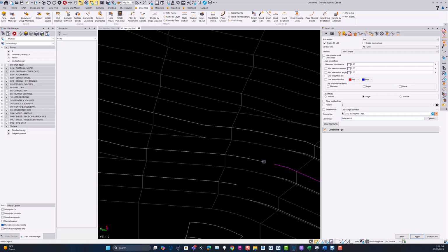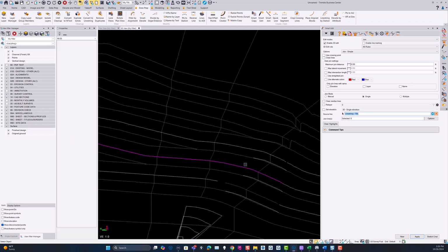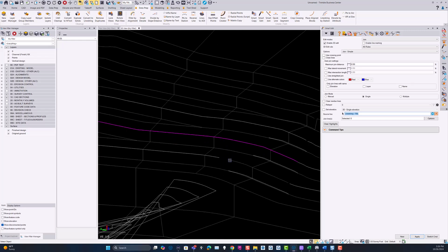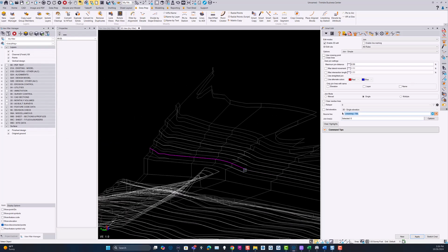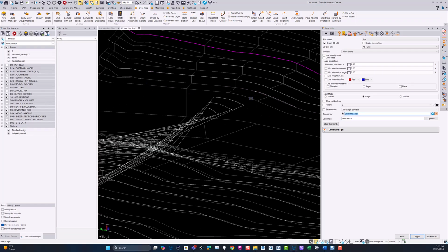And again, you can just keep going through here until you're done with the lines as you see fit. So very quickly you can use these commands, like in the 2D view or in the 3D view, to join things together, to break lines, to remove segments, to make these lines continuous. We don't have to pick them up in sequence. We can do them pretty much in any order between lines, which makes it extremely quick to modify and edit these lines.